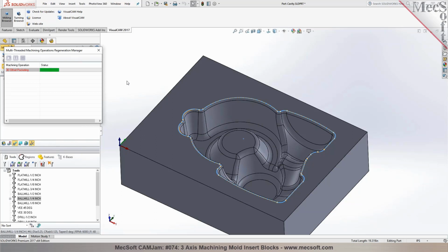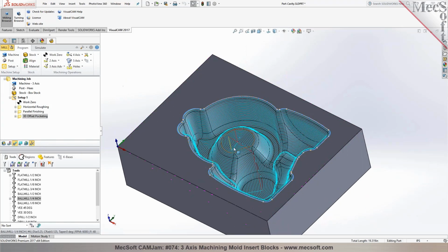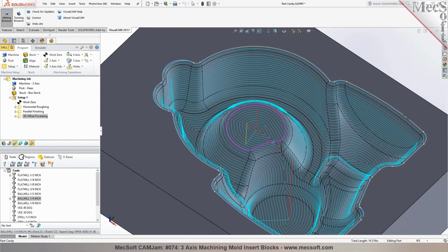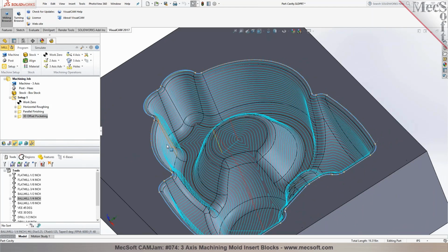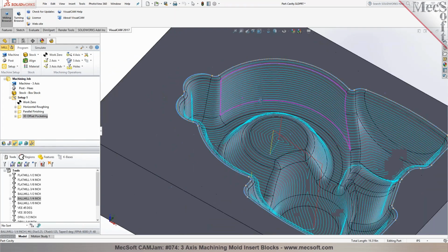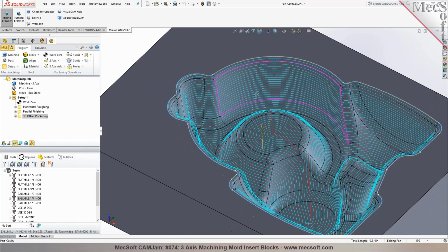As you can tell, this method has a little bit more computation involved, so it could take anywhere from a few seconds to a couple of minutes to generate the toolpath. Now while this toolpath is being generated, would there be any specific questions I can answer? No. Okay, so as you can tell here, the toolpath has just been generated, and you'll see that it creates a uniform 3D step over. So there's a nice transition in these areas as well. This method is called 3D offset pocketing.